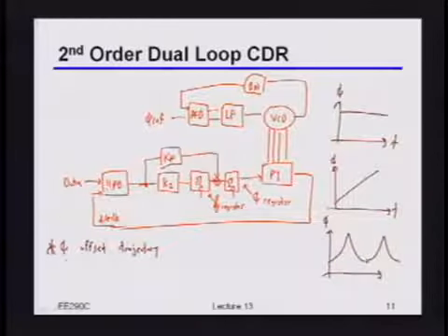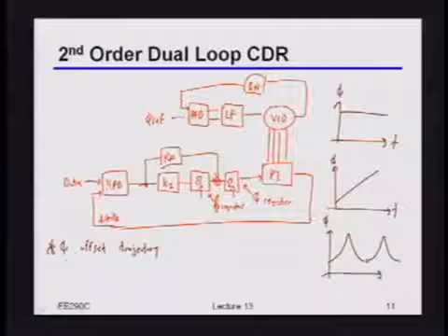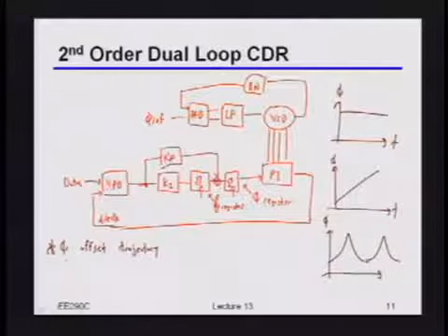It is indeed varying. It turns out in this particular case, it's actually being varied intentionally. Supply? Well, no, I mean, you could vary the supply to make this happen, but it turns out that people want things to look like this. They'll actually work really hard to make their PLL on the transmitter side intentionally do this. So any thoughts as to why you might want to do this? Oh, is this like spread spectrum clocking? There we go. It's spread spectrum.